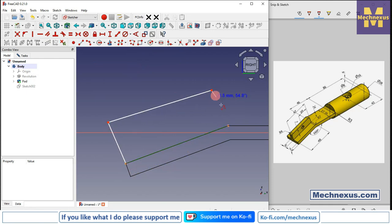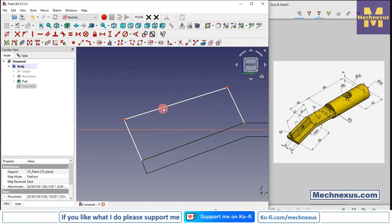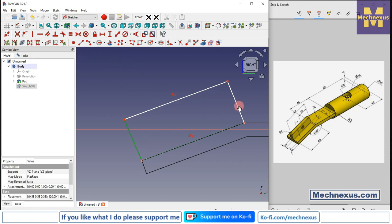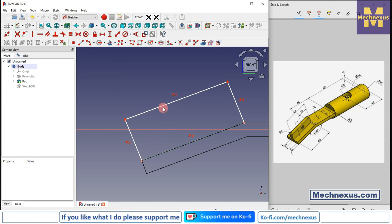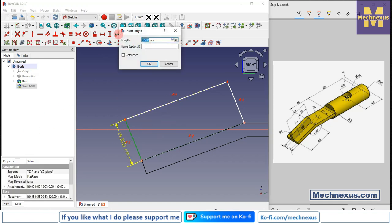Now we will select this polyline tool and create a rectangle. And now we will select this and add the parallel constraint, similarly this and this, and add the parallel constraint. And now we will select this line and click on the dimension, and this is of 14 mm.